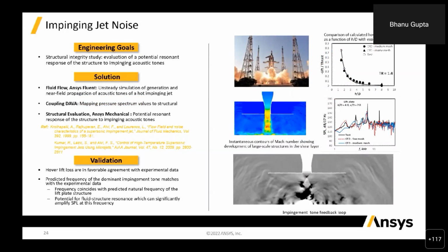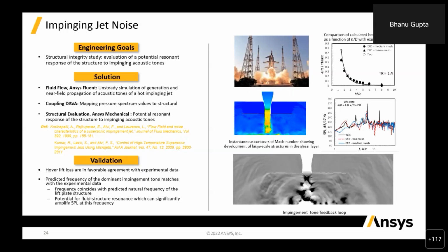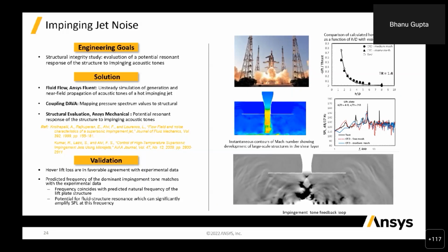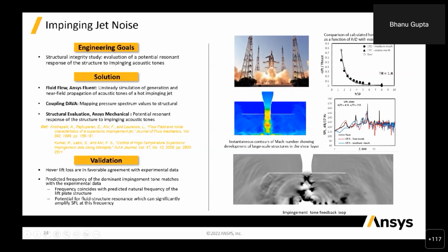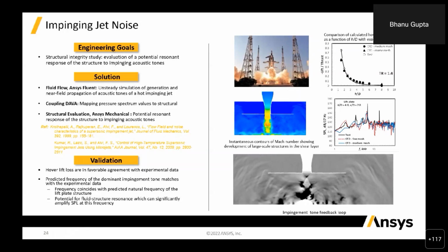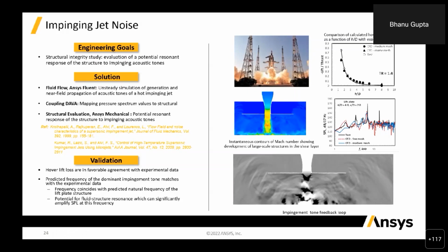In this example, it is more to do with, as the takeoff happens, how the bottom plate gets affected by the acoustic waves, the structural integrity study of the plate which is at the bottom. Now, this is again an example of a workflow, very similar to what was shown for the aerospace industry, for the automotive industry, where you solve the high speed flow on ANSYS Fluent, map the pressure spectrum on the bottom plate as the jet impinges, and then do the resonant study of